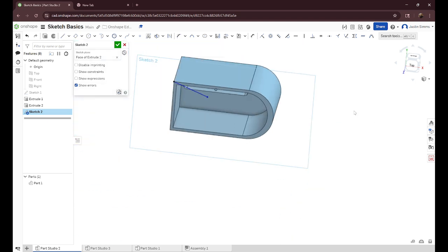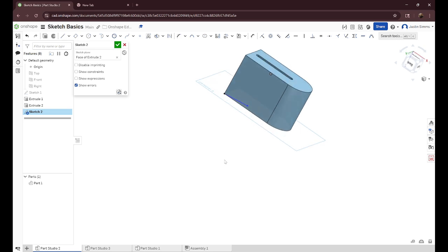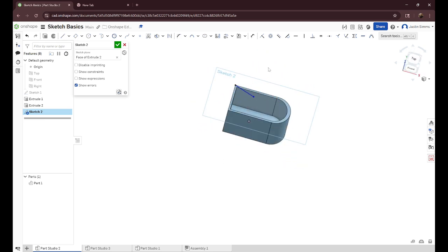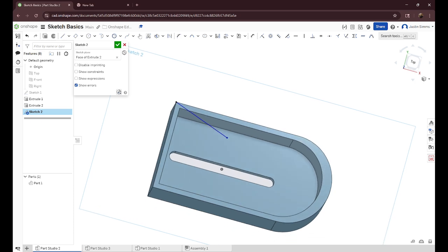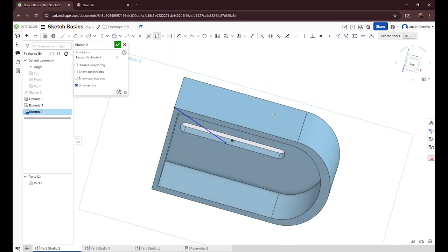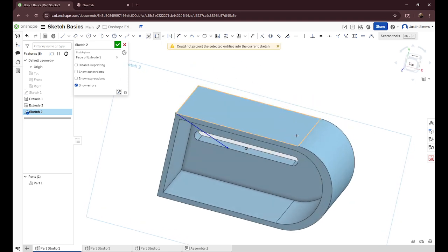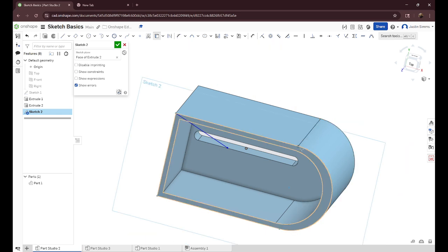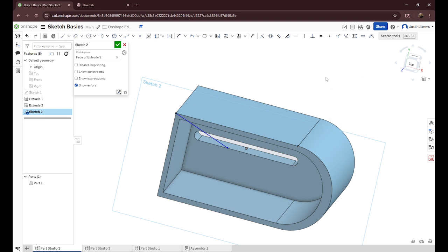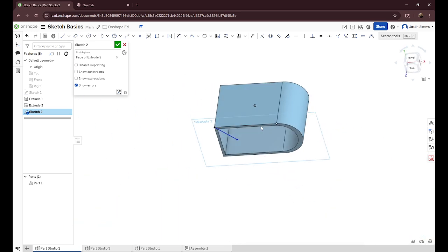Because whenever a line is coming straight out of a sketch, so it's normal to the sketch plane, you can't really use it well for the intersection or project. If you're trying to use it, it says it can't be projected. You can project a specific point, but you can't use the line. So if it's a curve, you have no recourse with it. So that's where I've really liked this Pierce tool. I'm still getting to know how to use it a little bit, but it's pretty useful.